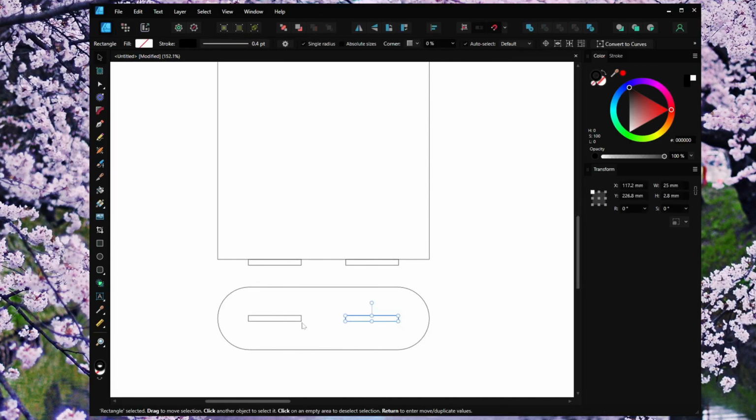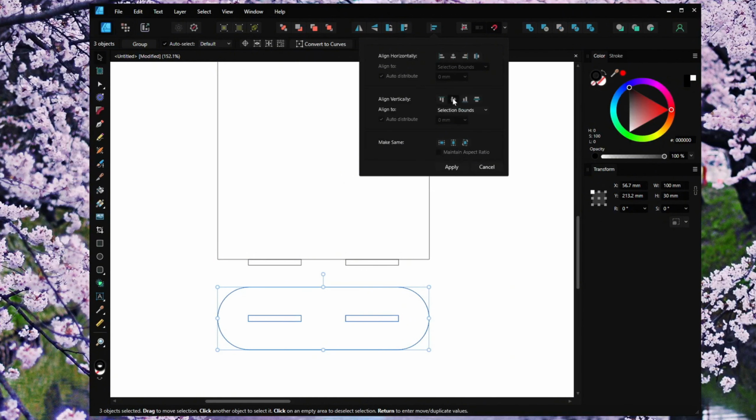We will change the width of these to whatever material you're using. So I will be using 3 millimeter plywood. So I will make this 2.9 millimeter to allow for the curve, which is the material that gets removed by your laser beam. So change them to 2.9 millimeter. Select them again and the base plate and make sure it's still centered.